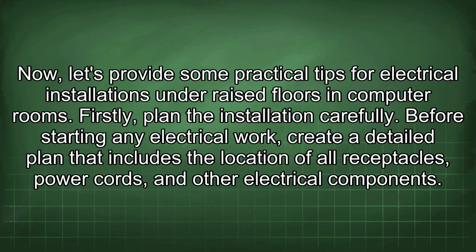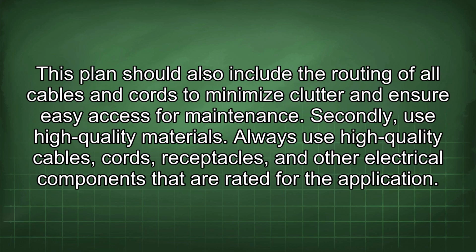Now, let's provide some practical tips for electrical installations under raised floors in computer rooms. Firstly, plan the installation carefully. Before starting any electrical work, create a detailed plan that includes the location of all receptacles, power cords, and other electrical components. This plan should also include the routing of all cables and cords to minimize clutter and ensure easy access for maintenance.